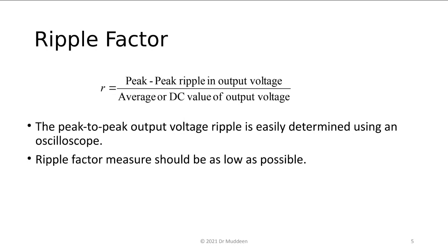That's a 1 volt peak to peak, from 4.5 to 5.5. At 4.5 volts, chances are you wouldn't be able to get the system to recognize a logic 1, because 4.5 volts may be too low for a particular device to recognize. And 5.5 probably works, but certainly not the lower end.